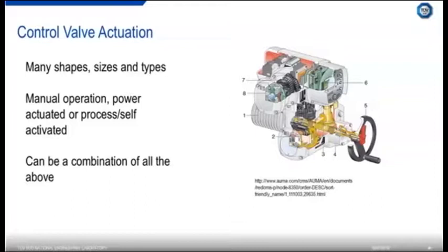To give you an example, some of NEL's test rigs are very high pressure, so our actuators fail open, because if they didn't, it could lead to a dangerous build-up of pressure. But on the other hand, you might have some process requirements where you want to contain your process fluids, so in those instances you might have the actuator fail in the closed position.